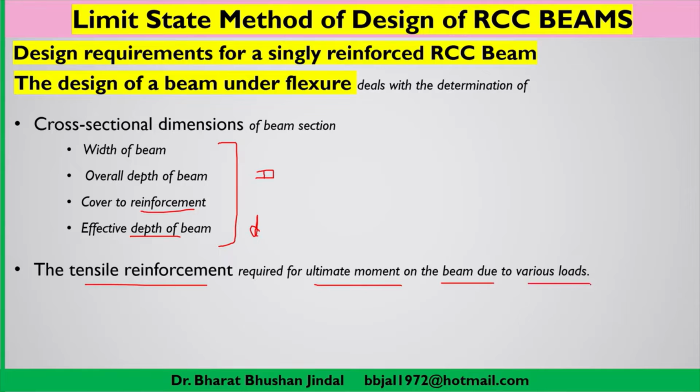So we are clearly aware from the last few lectures that whenever a beam is subjected to some types of loads, then due to that load, that beam will be under flexure. That means some bending moment will be acting on it, and we have to first of all calculate what is the factored bending moment, and then according to what is the ultimate moment which we are expecting that beam will be going to subject through its life period.